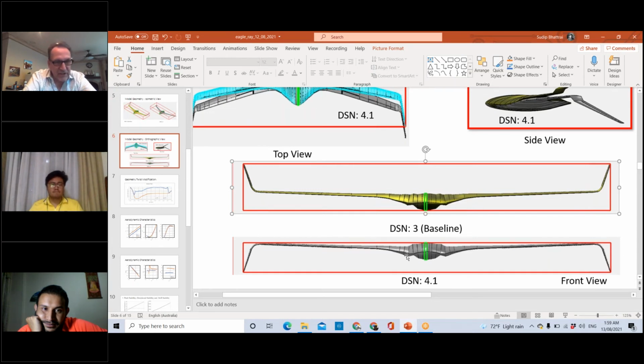And sometimes you have to use a little artwork. Yeah, okay, the cursor now is between airfoils. If the centerline is 1, then I have 2, 3, and you're between 3 and 4. Imagine taking a slice between 3 and 4, a new cut in CAD, and then take a cut between 4 and 5. You can tell already those two airfoils look kind of like each other. They're kind of similar in position. And then I delete the airfoil in the middle and I will get a natural smoothing, but that airfoil has been informed by its two neighbors.